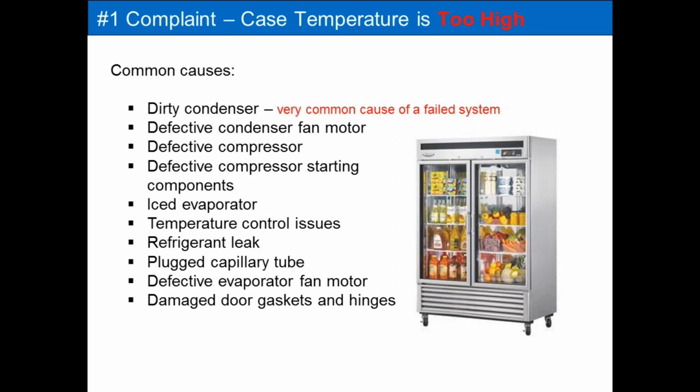And what we're going to cover tonight is all of these possible scenarios and how you can determine which one of these possible causes is causing this case temperature to be too high. We're going to talk about dirty condensers, which by far is a pretty common reason for failures of these systems. Whether the condenser being dirty is the immediate failure, or the condenser being dirty caused another failure, for example, a defective compressor.